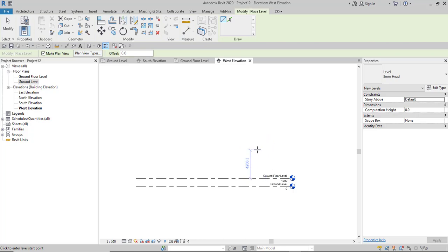So I'll come into my software, come into the left here, where this marker starts. And so when you align it with it this way, you realize that you see some dimensions, and then you see some broken line also showing that they are properly aligned. When you move to the left, it disappears. When you move to the right, it disappears. Then when you align with it, you see that broken line. Then you see the dimension you want. So you can just drag it to the dimension you want. Say 3000. And then start drawing your level this way. Okay.